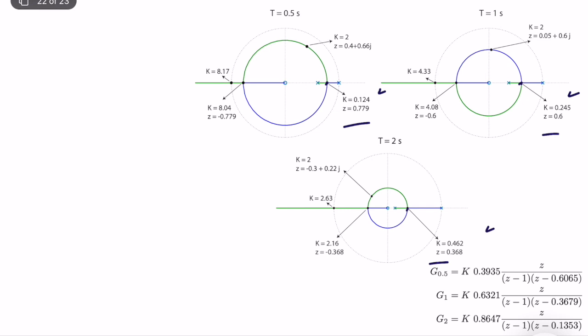It's bad because, as you can see, gain is very little, very small, which means that we will get a bad performance in terms of a different location. For example, k is equal to 2. But maybe if we compare critical damp locations, we can get a different results. Good. So what we will do is let's look at the overshoot. 0, right? Because it's critical damped.